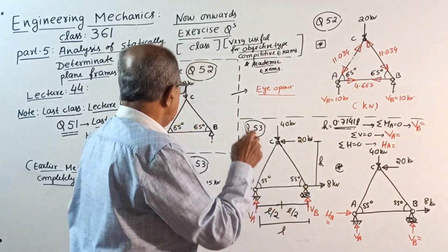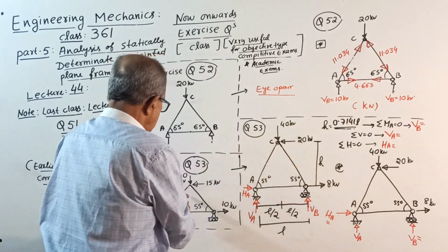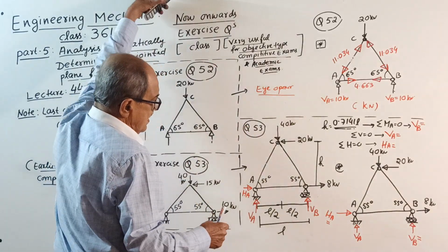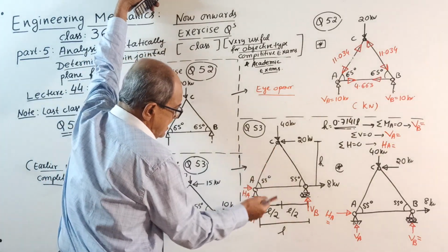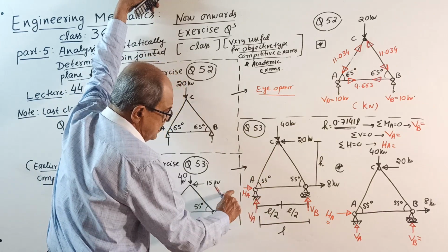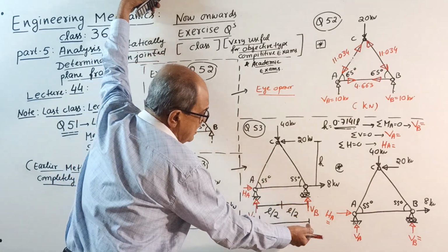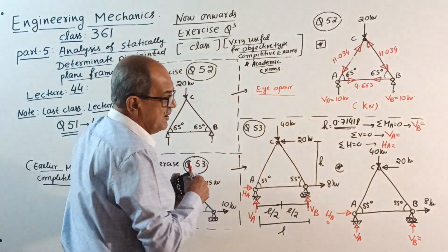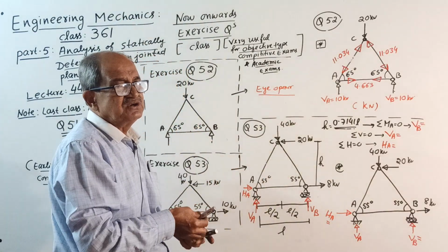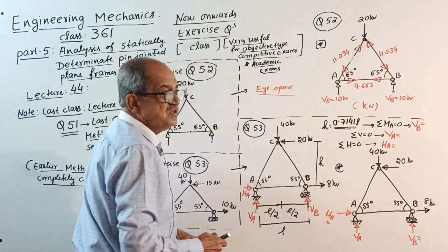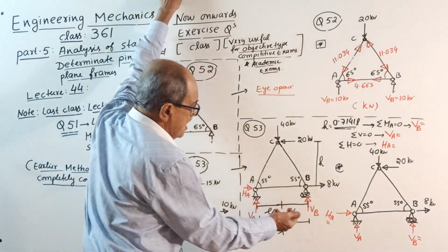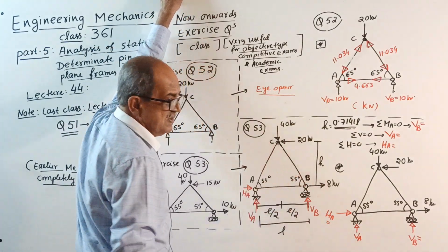Okay. Now, question 53. See here. One hinge, one roller. As usual, hinge has a vertical reaction and a horizontal reaction, and the roller has a reaction perpendicular to the plane. Since it is horizontal, first of all, I should not tell all these things now. Too late, sorry. It is told thousands of times. So, RB equal to VB.